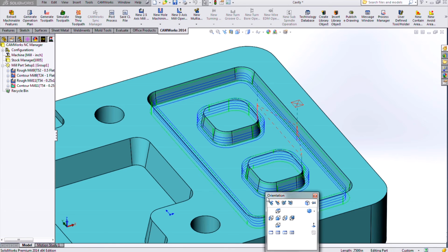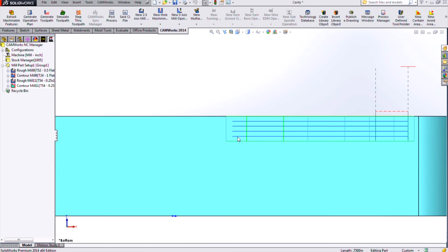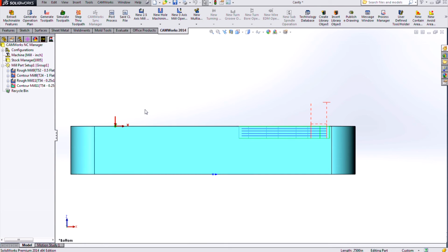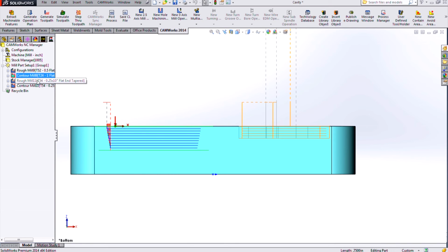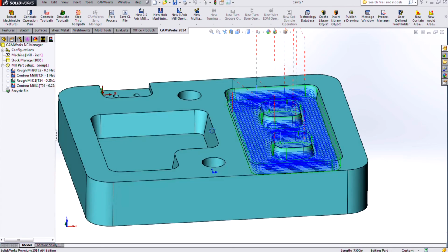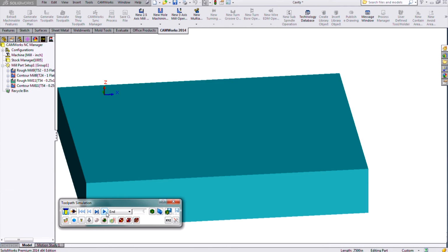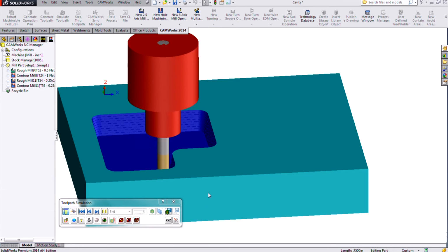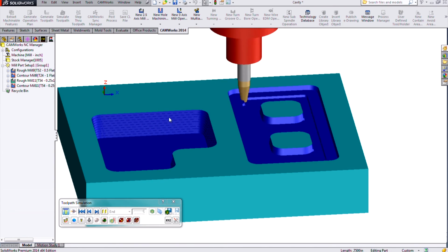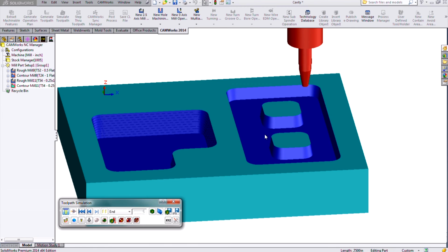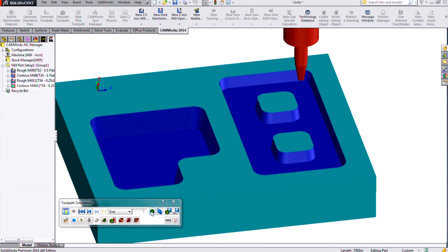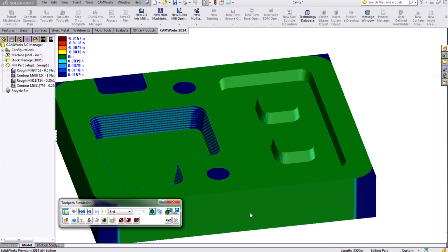We can see that the tool path in this case is straight down, which is what we want when we're using the tapered end mill. When we're using a flat end mill to cut a tapered pocket, we want it to ramp down like this, but for our tapered end mills, we want to make sure it's straight. I'll simulate through this entire machining operation, and we can see the auto detect pocket on the left versus the pocket with our tapered end mill on the right. If we show difference, we can see that using the tapered end mill, we're accurately representing the pocket to a degree that you'd have to use really small step downs to achieve.